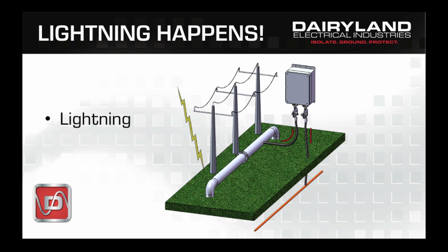Lightning is particularly a problem for southern states and in Florida, not as common an event for California, but nonetheless, everyone must deal with the potential for a lightning event. We don't necessarily know the polarity of a lightning hit, so the decoupler must respond to both positive and negatively charged events. In the case of our standard decoupler, any potential less than -3 volts or greater than +1 volt will trigger the decoupler into conduction. A lightning event has potential well outside of those numbers.